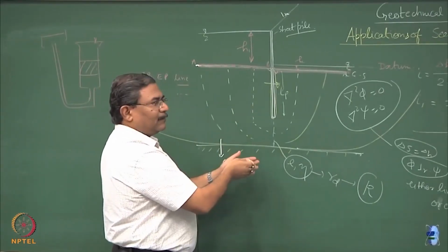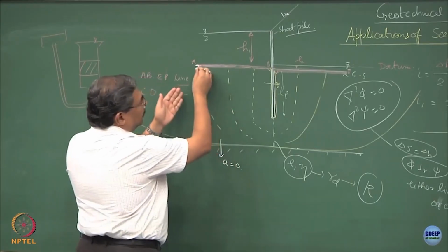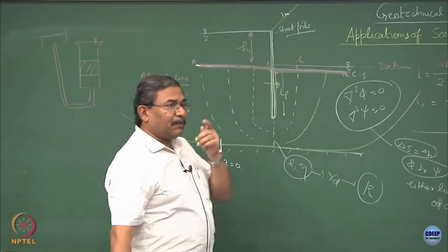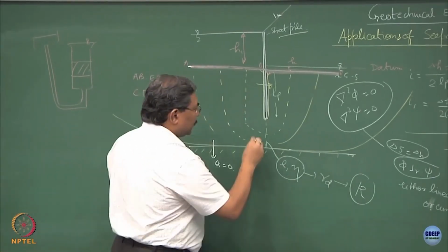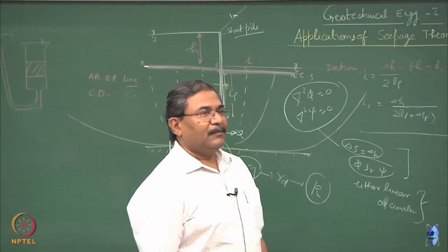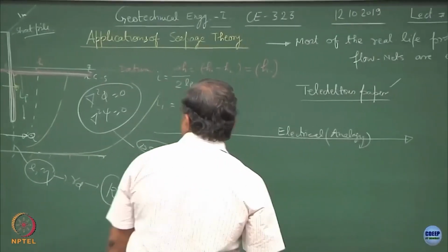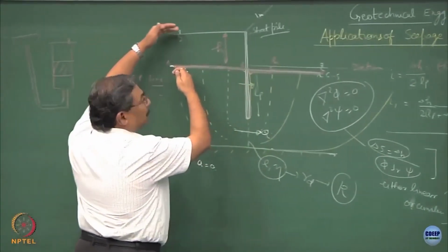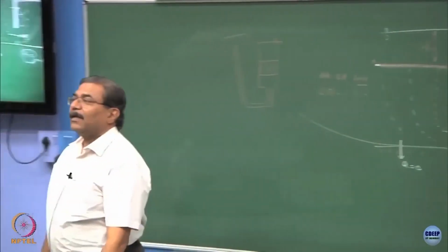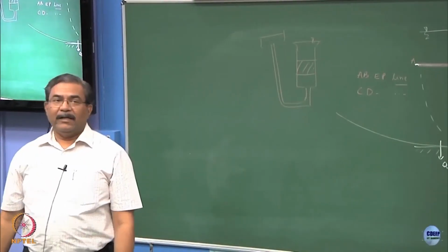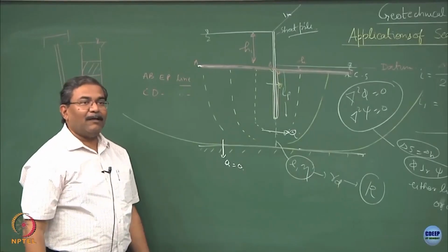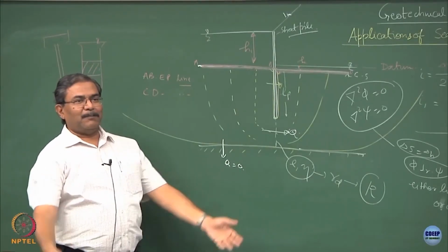One is, okay, we have established the flow net. So, all these become the flow lines. The whole idea of doing this flow net is, as somebody said correctly, I want to find out what is the discharge taking place across the sheet pile system. Because what is your whole intention? The whole intention is that this water should not be lost at all. Polavaram Canal is a beautiful example, clear. You have a lift irrigation system, pervious land, even if you store water, everything will seep through. What is the point in spending crores of rupees?